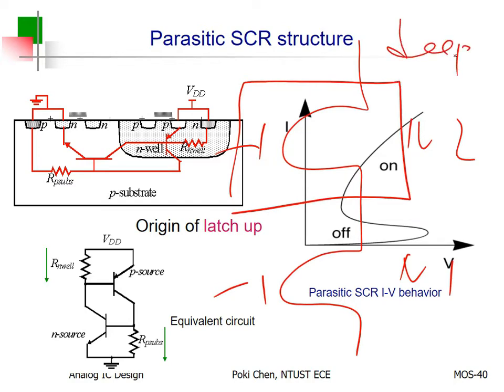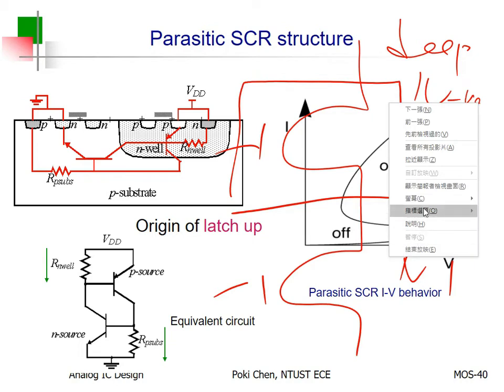And you cannot apply N well. No. If you apply N well, inside the N well, you can only fabricate PMOS. Okay? You cannot fabricate NMOS inside N well. Then it will become depression type. It doesn't make any sense. Okay? So we need the help of deep N well. So what is deep N well? Okay.